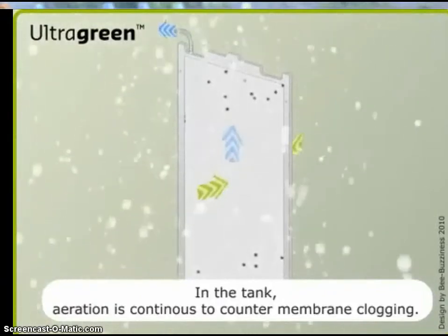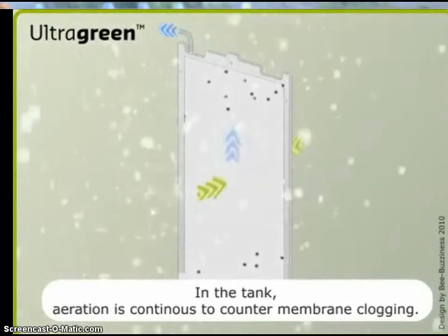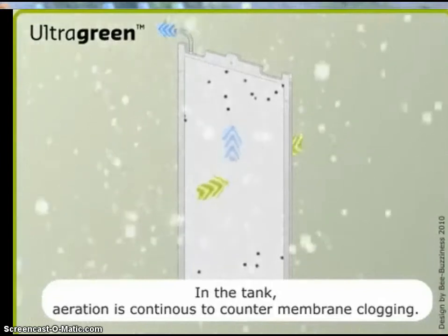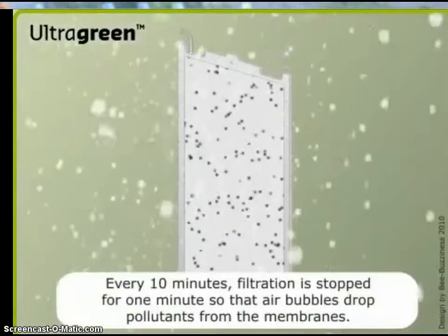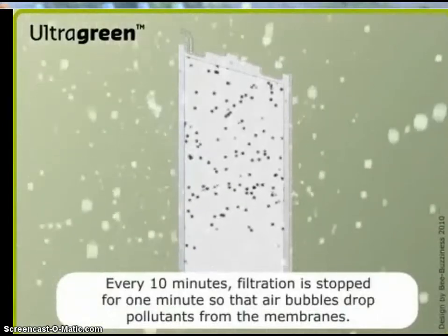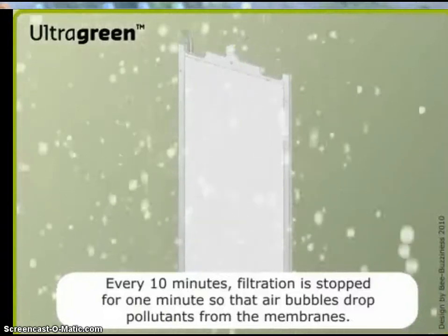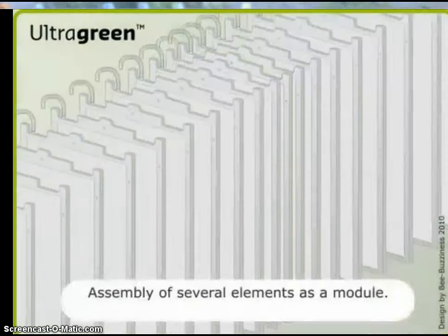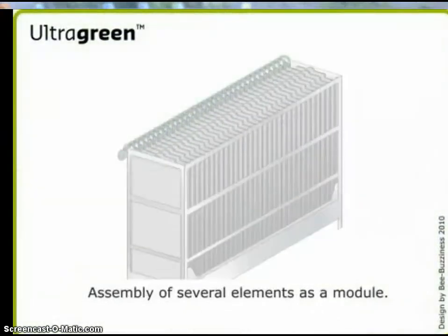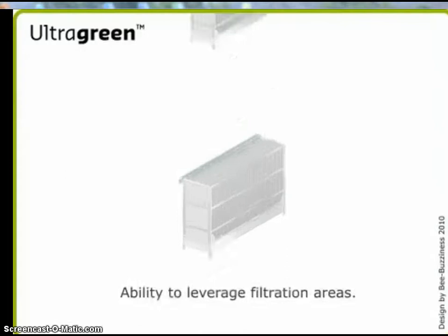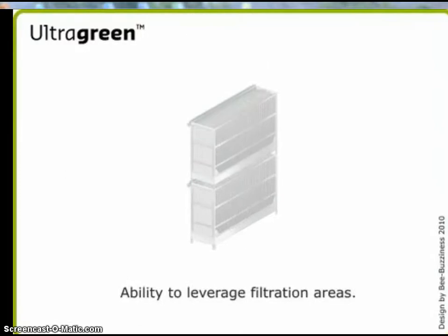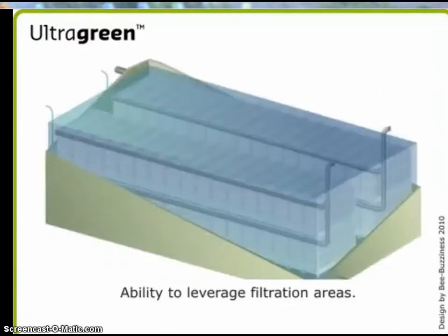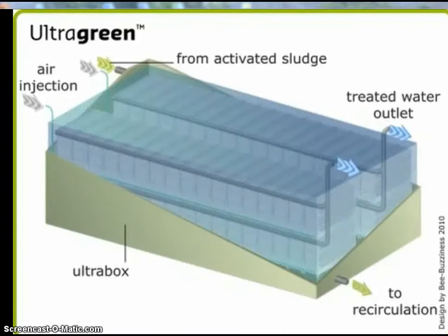Based on the fouling effect, or by measuring TMP, transmembrane pressure, it can be shut down, and the deposition can be cleared by stopping the negative suction head created at the top end. So this is a cassette, and this is a whole module being shown to you. This is how the MBR will work and can be used.